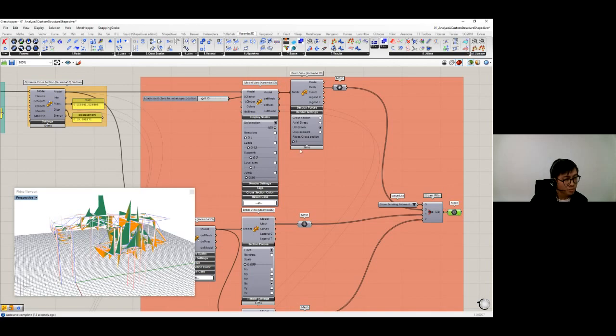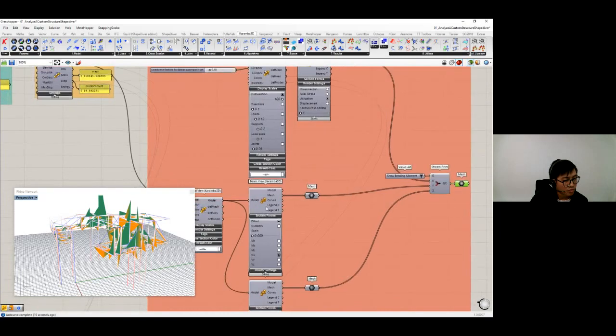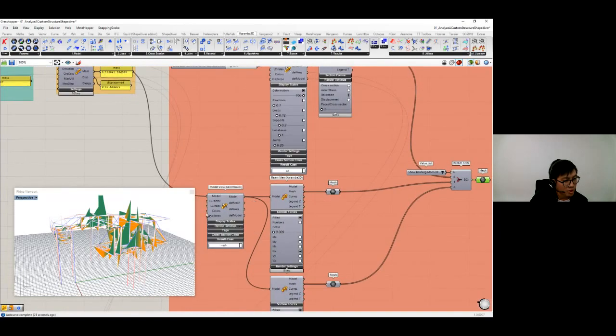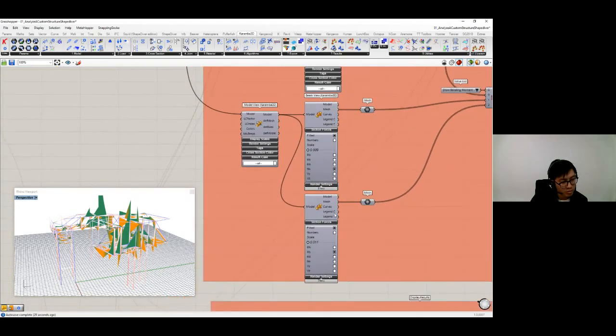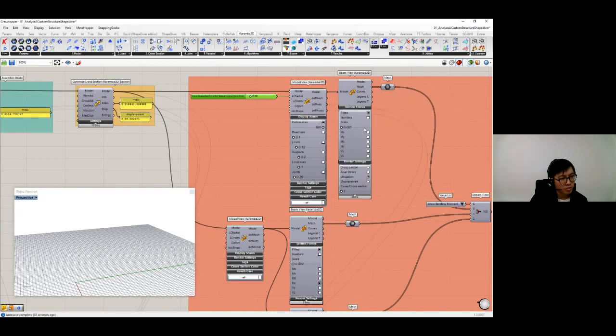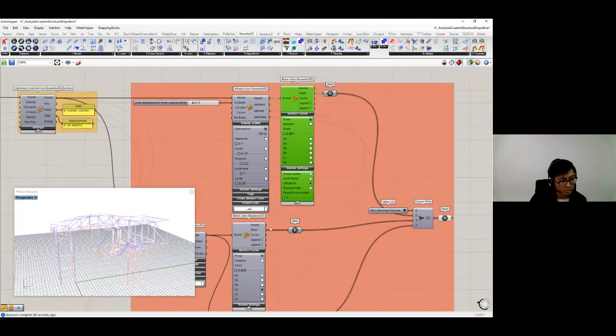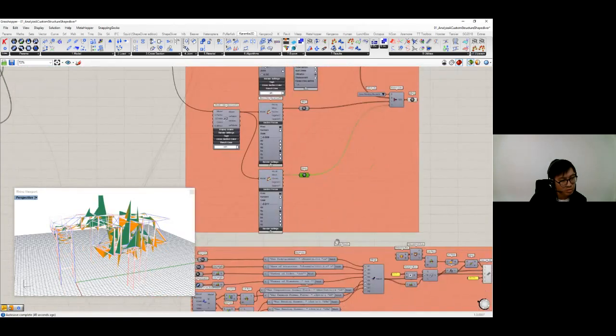The reason why I've split it into 3 segments is that it's not currently possible to show the deformation scale in the beam view, or the beam view in the normal forces and the bending moments output, because this slider, as Clemens mentioned, is basically a factor multiplier. So if I was to extract the section forces from this component, you're actually multiplying the loads in our setup. And this is why I've got 3 different setups here for the mesh output.